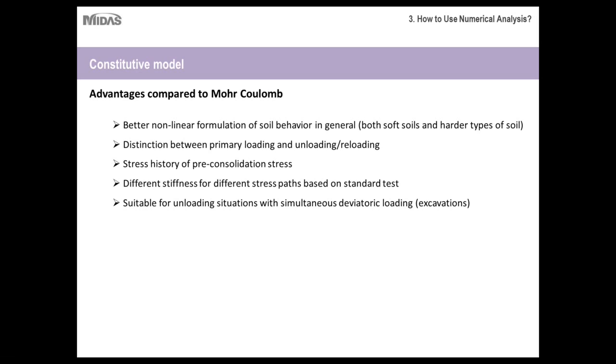Then the stress history of pre-consolidation stresses can be accounted for when using advanced material models, along with different stiffnesses for different stress paths based on the standard tests. This is just what I discussed about the different Young's modulus.